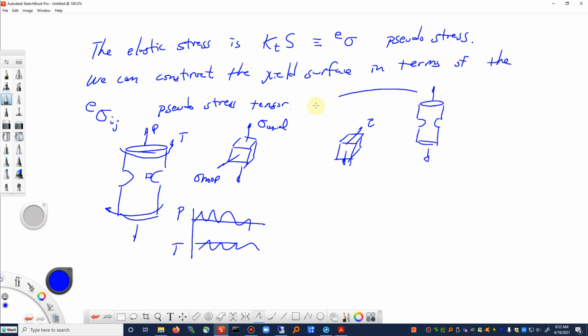So this corresponds to this case, and if I have the same bar, I do a completely separate static FEA, and I do torsion, that would correspond to this case. Basically what I'm doing is finding the influence coefficients for each of those separate loads.